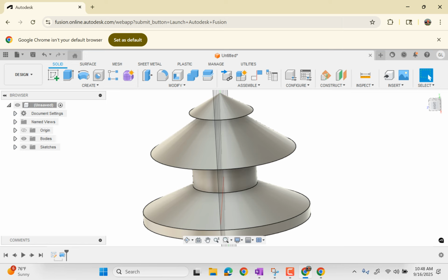So one thing to remember about this is you're doing the projection of the shape you want, but remember to only do half of the projection if you're going to rotate it 360 degrees. Otherwise, you have material crossing over material and it can cause errors. Or you can do the whole projection, but then you have to tell it to only rotate 180 degrees, because that's the limit before it starts crossing itself.